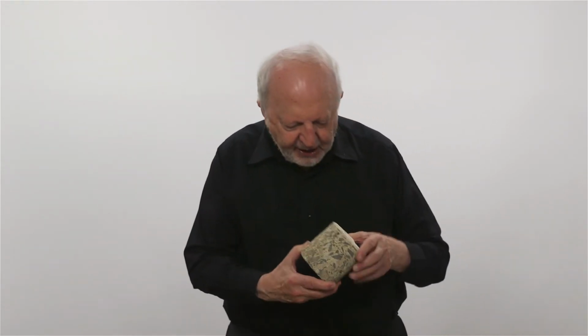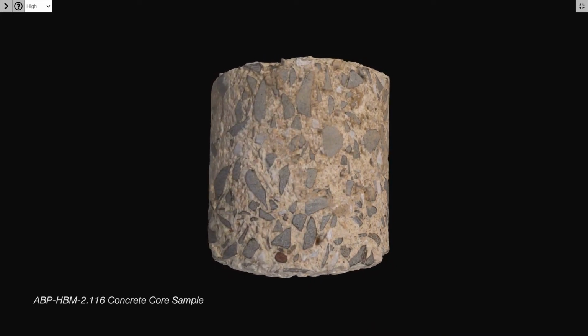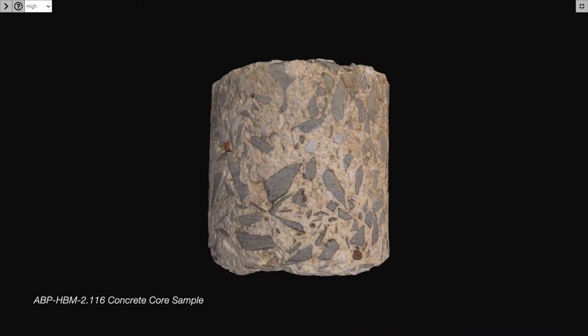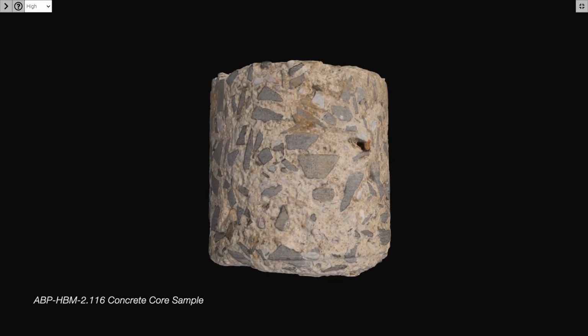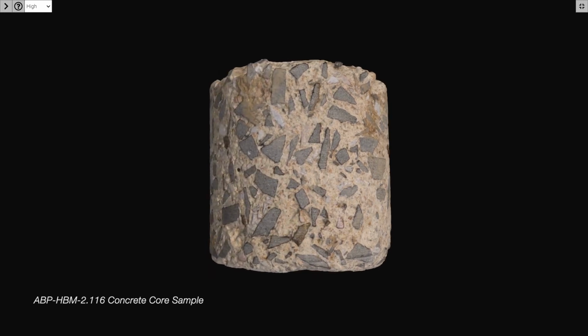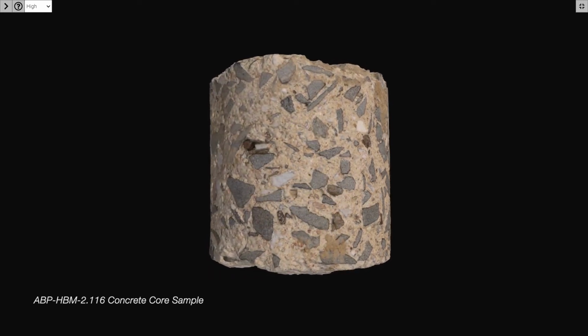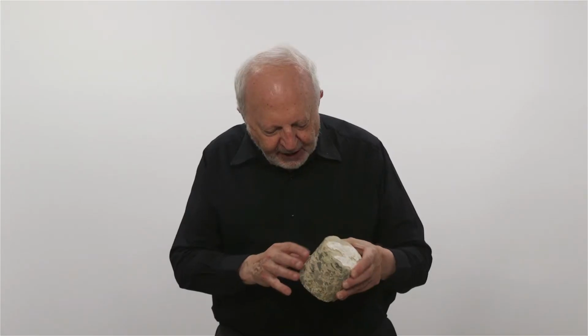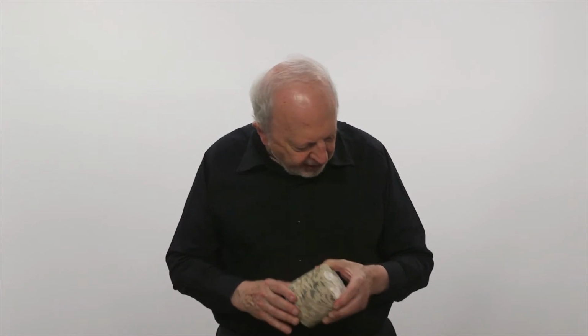Now, when you come to true concrete, it's a material, of course, very strong like this. This is a core sample, which will be taken by an engineer, and it cuts right through all the aggregate, the stones inside it, which are, as I said, sharp stones in this case. Usually when we're investigating buildings for historical purposes, we're not so concerned to get a sample like this, which can be to standard size, can be tested for strength, but to get the details of these stones and the content of the material. So we find rather different components.